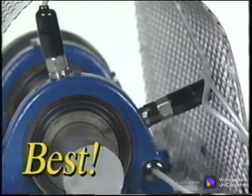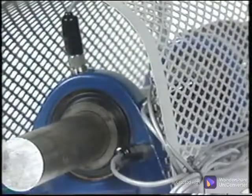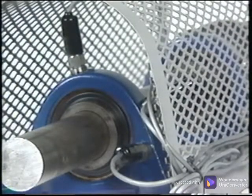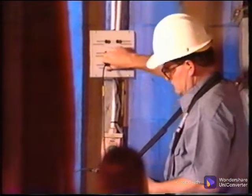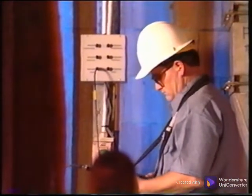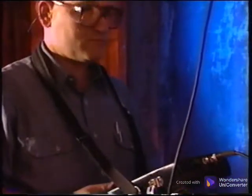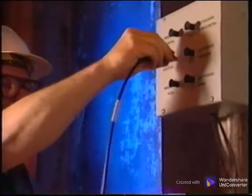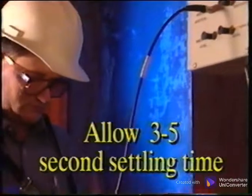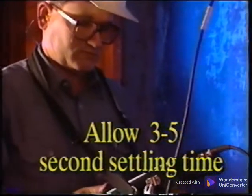The best way to measure guarded pillow block bearings is to install permanent sensors at the measurement locations. These sensors are then wired into a panel that has terminals for BNC cable connections. The measurements can be made without compromising safety or data quality. Remember that in most instances, the analyzer will be providing power to these sensors and that the sensor receives an electrical shock and requires a 3 to 5 second settling time.